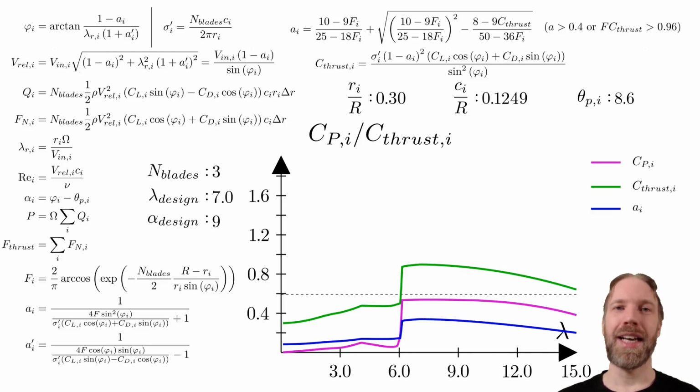In reality, if the tip speed ratio changes past this jump, the speed of the whole wake would have to change before we reach the steady state conditions. Hence, we can expect a much more smooth transition in reality. It can also be noted that the chosen airfoil has poor stall characteristics with a large drop in lift force when it stalls, which contributes to this jump in power.